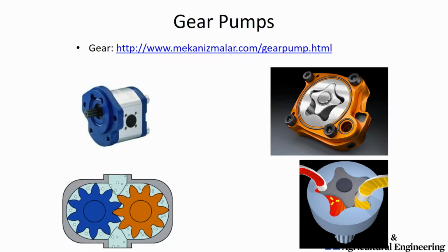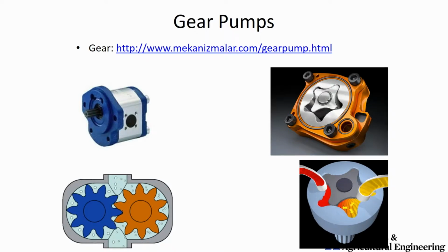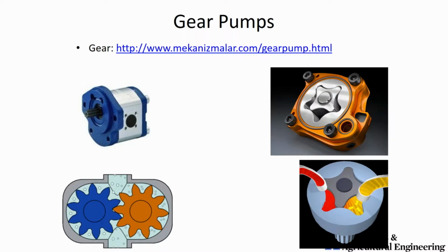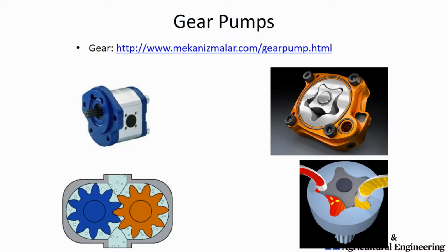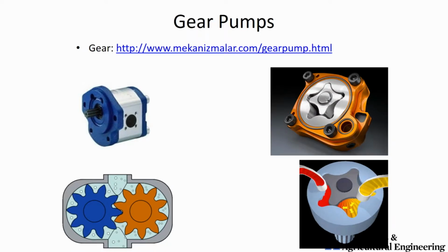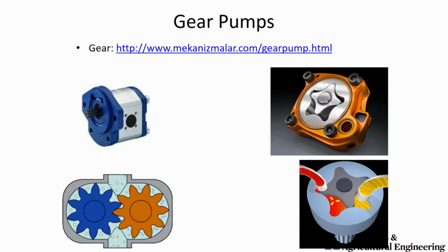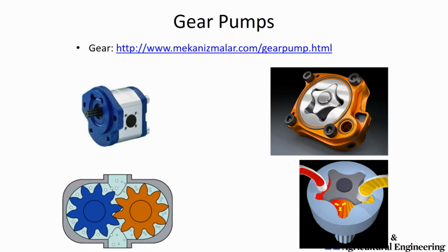You see a picture of one up above there. They're somewhat unique in their appearance because they're generally an oblong shape, and the shaft comes into one of the two gears. So you can see that the shaft does not come into the center of that oblong, but it comes into one of the lobes on the side of it. And so you can look at that shape and say right off, hey, that's an external gear pump.